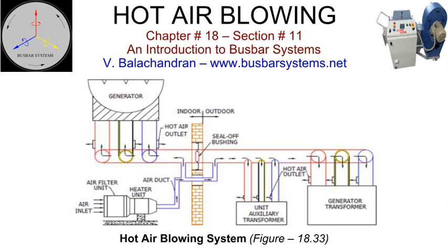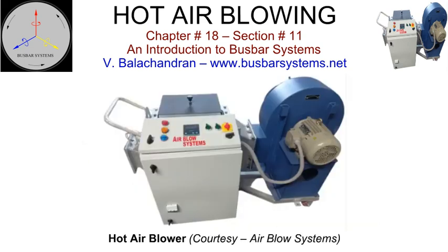In the case of bus ducts, hot air can be introduced at designated locations from portable equipment with a flexible hose. Unlike in an isolated phase bus, bus ducts have several bolted covers along its run where there could be significant leakage of air. The hot air blowing equipment comprises a variable speed motor-driven centrifugal blower to deliver air at